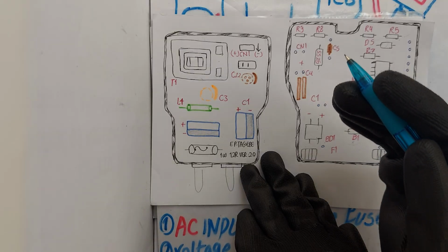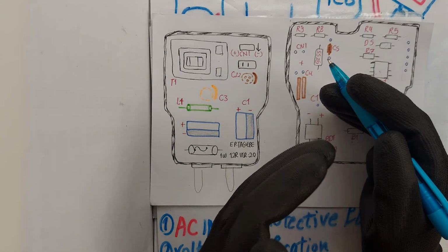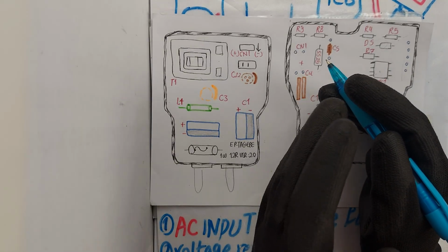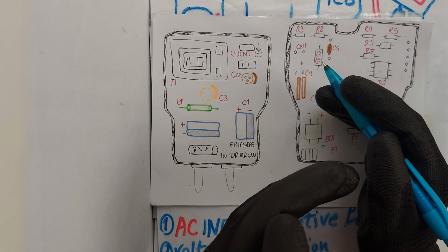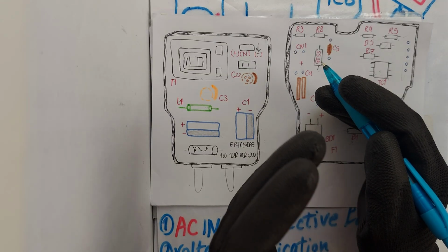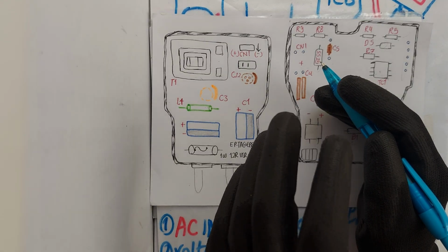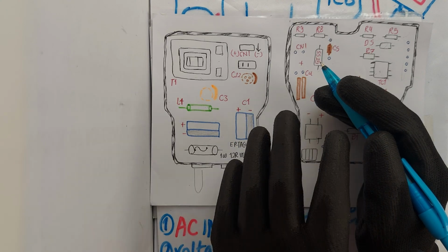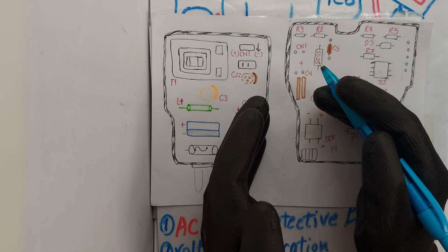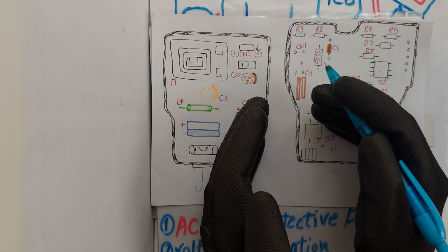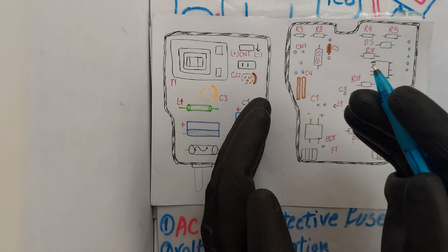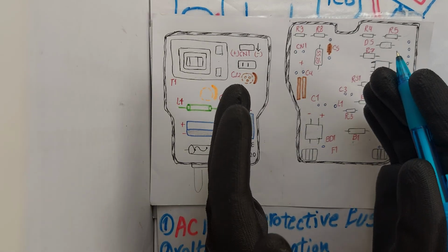Designed to operate in the global voltage range of 100 to 240 volt AC, the switching method, unlike linear regulators, reduces energy loss and allows smaller transformers and components, with precise control of approximately 0.7 ampere current.